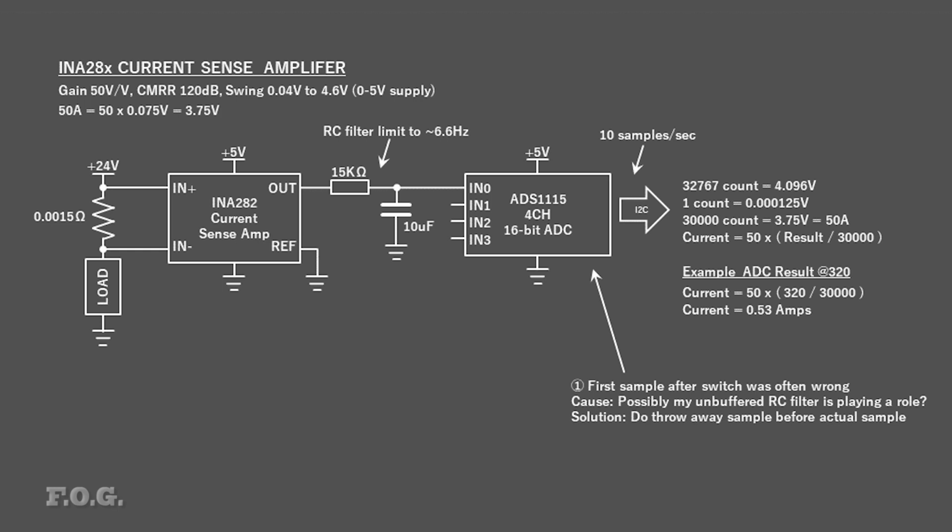The second and more excruciating issue that I suffered was terrible inconsistencies with the gain, depending on the bus voltage or what the inverter load was doing or whatever. Sometimes it would just float around everywhere. In fact, this problem ended up being so bad that only 4 of the 20 chips that I had on hand were somewhat usable. And it was a real struggle trying to make sense of this problem. In fact, I spent well over a month trying to solve it.